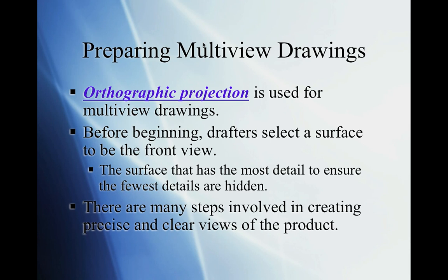But first thing, you've got to make sure you use the front view, and that's the one that has the most detail and the fewest hidden dimensions or details on it. Okay, so again, orthographic projection is the same thing as what we call multi-view drawings. We just create this drawing so someone else can complete your product.